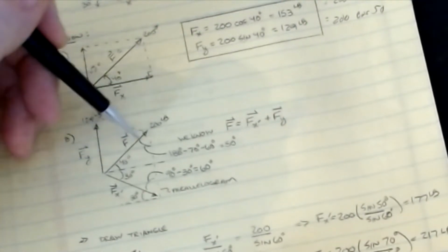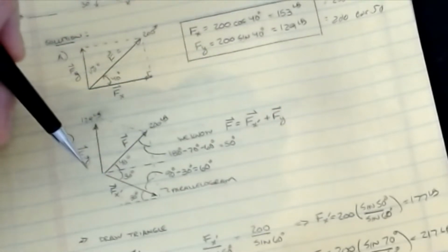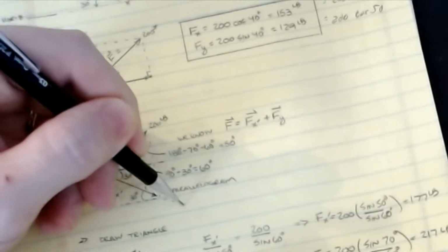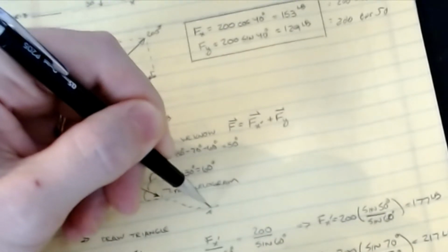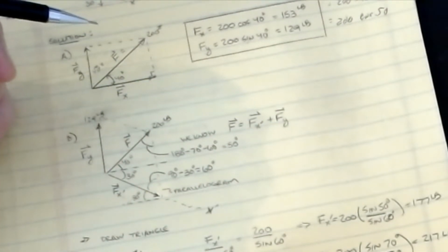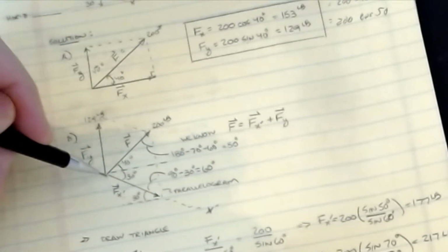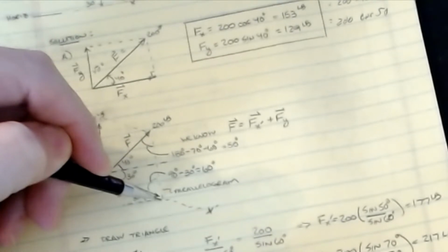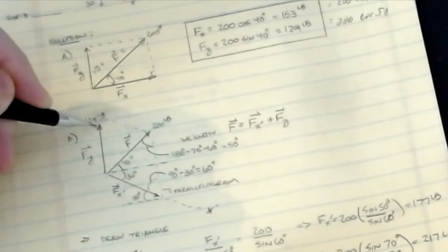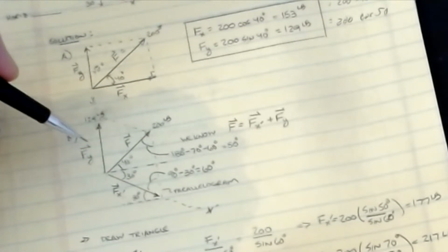All right, so the same vector, 200 pounds, measured at 40 degrees off the horizontal, and this time I'm going to set up an angle of 30 degrees below as being my X prime axis down there. Okay, so what we know is that if we play our parallelogram law, there is a vector along the X prime axis, F of X prime, that goes down to some amount, and then there's an Fy vector along the y-axis, because y is still up this way.